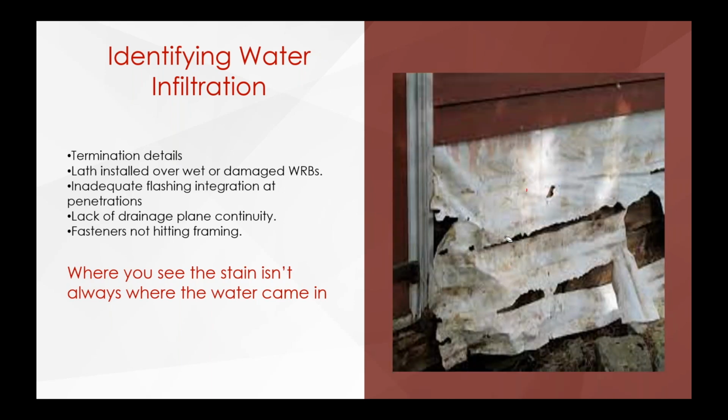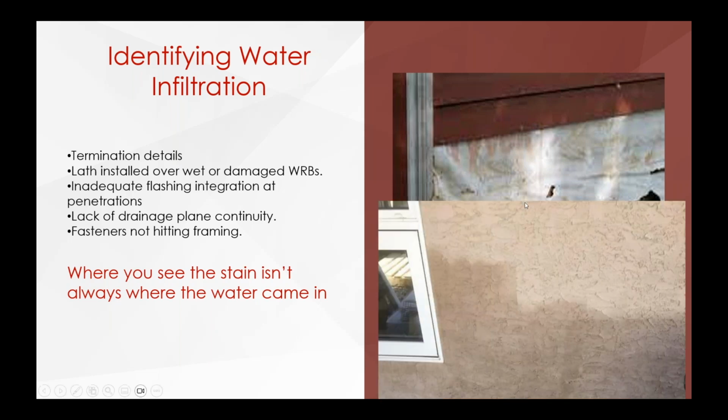So other ways here. Now, I know this is an exaggerated picture right here. I'm showing damaged water resistant barrier. The reason why I'm showing this is we had one project down in the town that I live in that halfway through the project, the contractor went bankrupt and it sat there for a year. The water resistant barrier was getting exposed that entire time. Now, I don't know if they came back and fixed it or not, but that is one thing that you want to watch for. And a good building envelope consultant will mark that and look for that later on. So you want to make sure you're going over good water resistant barrier.